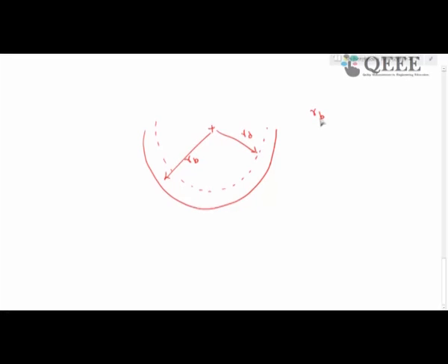So, let us be clear on this: there is a base circle Rb. From the same center there is a dedendum circle which, for the parameters taken, happens to be lesser than Rb. So we are talking about a situation where Rb is greater than Rd. Now, when you say this is the dedendum circle, the tooth profile has to extend up to the dedendum circle, but technically the involute cannot be present, because an involute is generated by unwinding a string from the base circle, not from the dedendum circle.